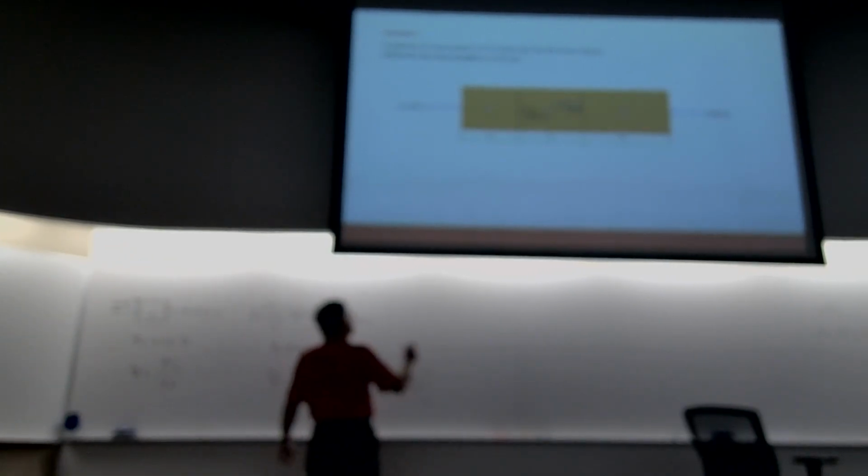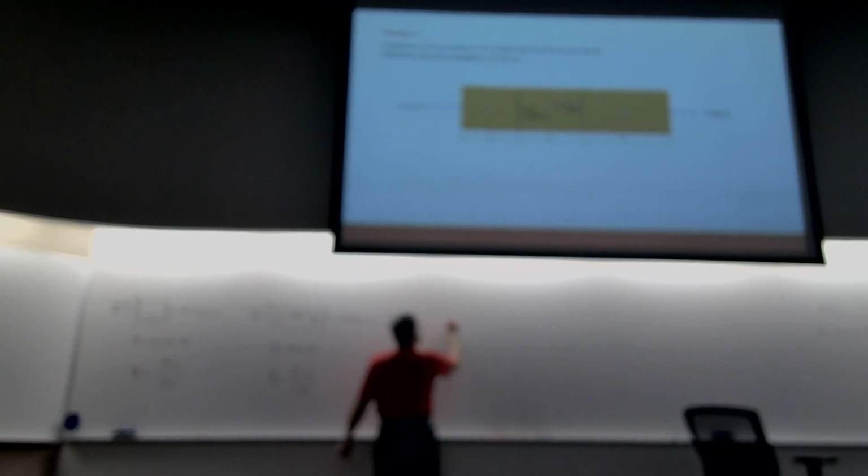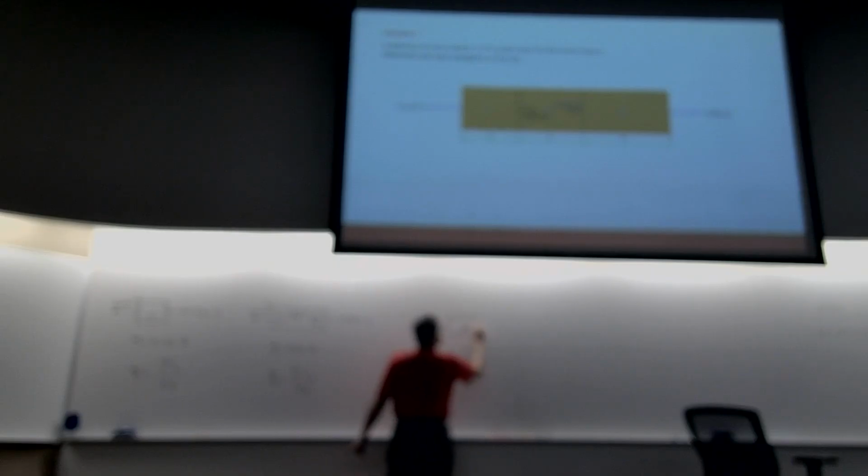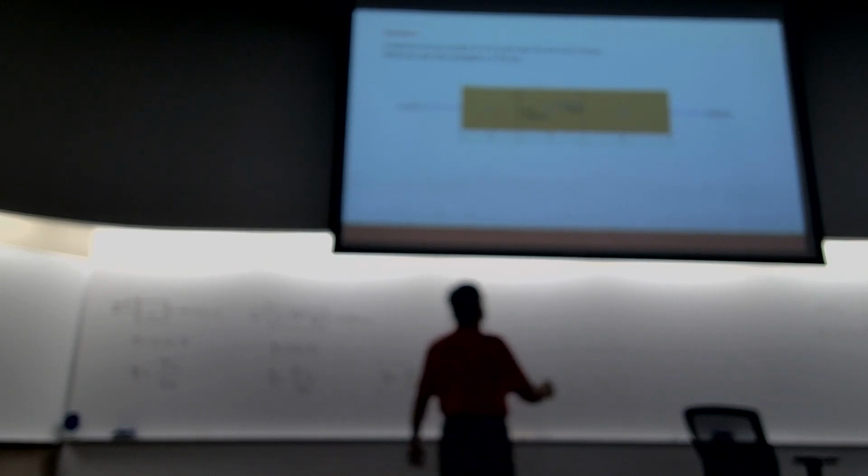I'm sure you know what the next step is. We're going to make a cut in segment 3 and look at what? Everything all the way to the left or all the way to the right, whichever is easier. Obviously for segment 3, it's easier to look to the right. So cut here, segment 3. Here we have 9,000 pounds.